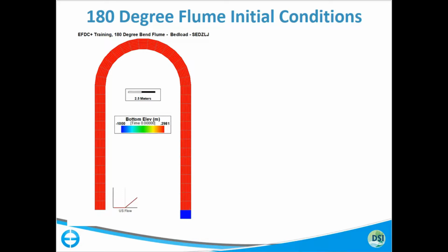I put it at the end of the computational domain so that any water that flows through the flume and out of these bottom cells is captured within the model domain, so we can calculate mass balance. And we'll do that this afternoon. I'll show you guys the tools that we can use to do that. So this is a nice little closed system test. I think it's a very useful little application.